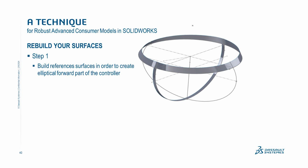They're especially important and required for fill surface because fill surface lacks a few options like boundary does to do normal, to do draft, to do things like that. The fill wants to derive its shape from its surrounding boundary surfaces. And that's why it's important to create these reference surfaces, especially when you're using fill.